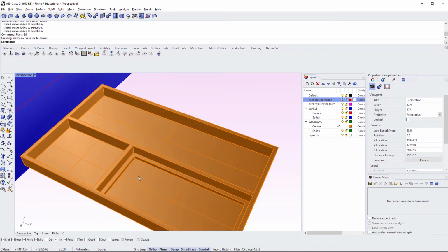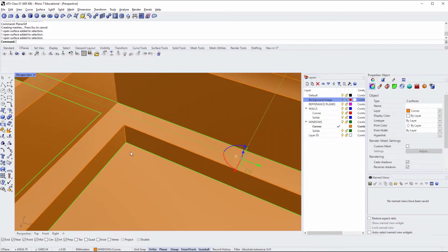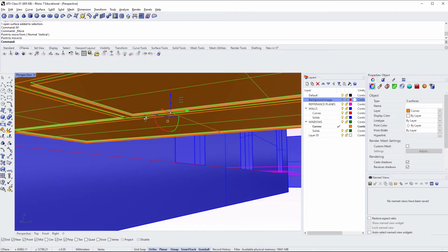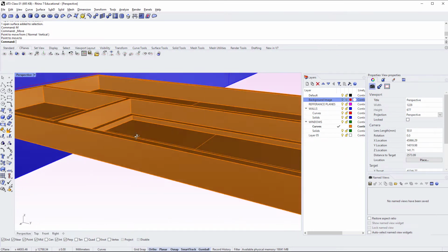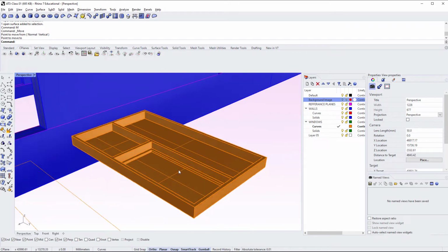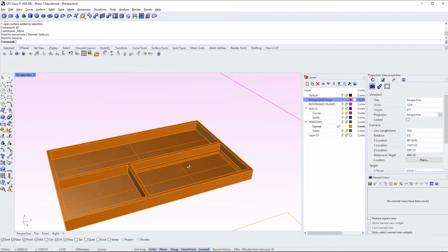And then the final thing I'll do is select all 3 of those glazings. I'm going to zoom into this corner here and move them upwards, halfway through the awning panel. So I've moved them 20 mil offset back. Now of course glass has a thickness, but in this instance for a design model we're not going to worry about it. It's just going to be a planar surface.